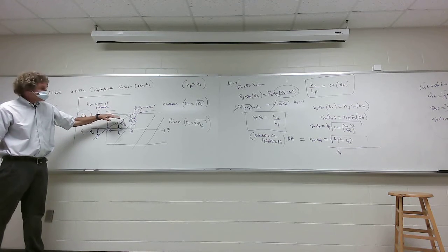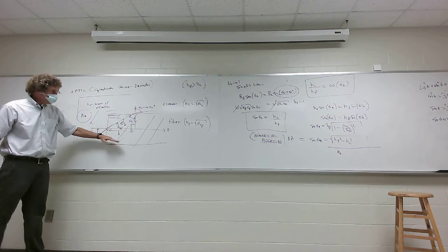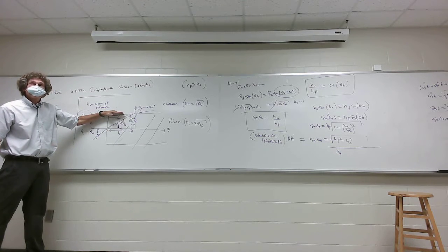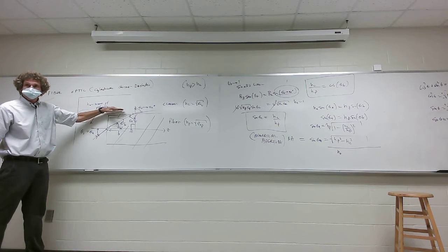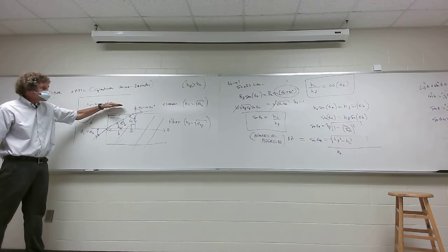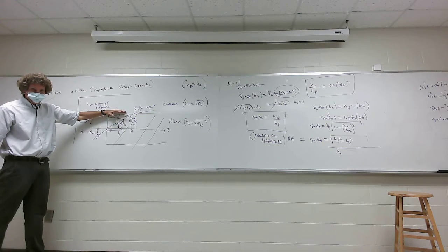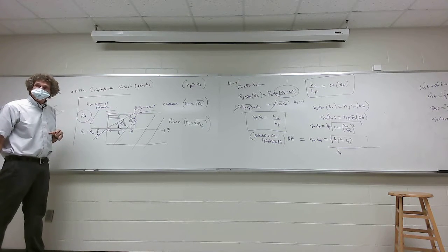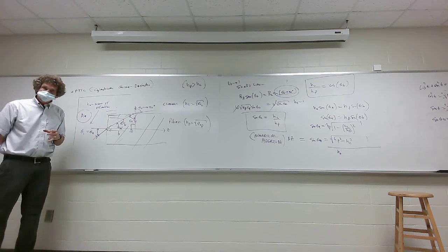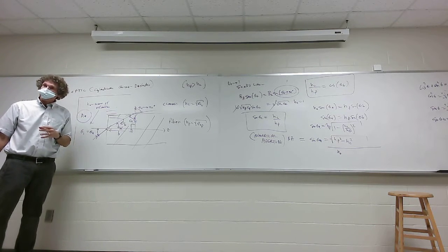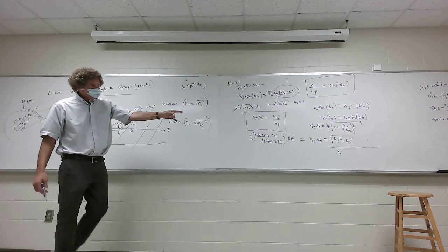Most of the time what they do is they have the fiber in here, and then they'll put a layer just on the other side of it that will have a slightly different index of refraction, and then another one, and it will gradually approach the cladding, but it'll be over a very small region. Just appreciate that can happen. That's called graded index material, or graded index fiber. The term is GRIN. We don't worry ourselves about the material science aspects. You just have to appreciate what goes on. Primarily, that's the thing you worry about.